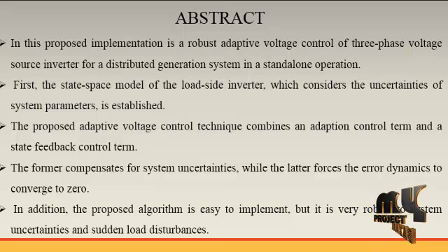In this implementation, a stability analysis is also carried out to show the robustness of the closed loop control system. The proposed control strategy guarantees excellent voltage regulation performance, that is fast transient response, zero steady state error and low THD under various types of loads such as balanced load and nonlinear load, and the corresponding output is compared with the PI controller output. This implementation is done in the MATLAB simulation environment.